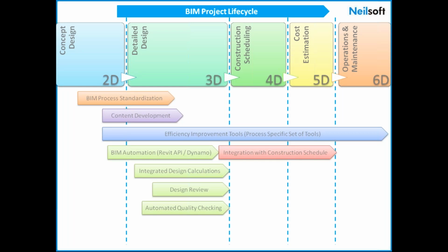Then as we move from 3D to 4D and 5D, the next important step is construction sequencing, and attaching that sequence to your construction activities. And that is where various tools are being used in the industry, right from MS Project to high-end applications like Oracle Primavera. And that is where integrating your BIM data, the BIM model itself, with your construction schedule, creating your construction sets and assigning these construction sets to various construction tasks within the schedule, is something which, with two different systems, becomes very difficult.